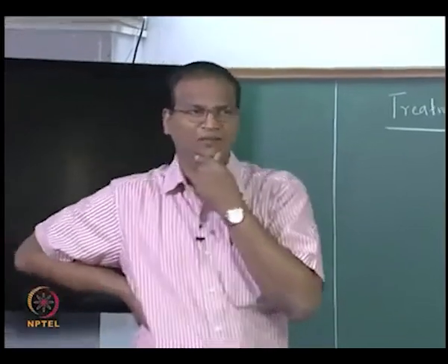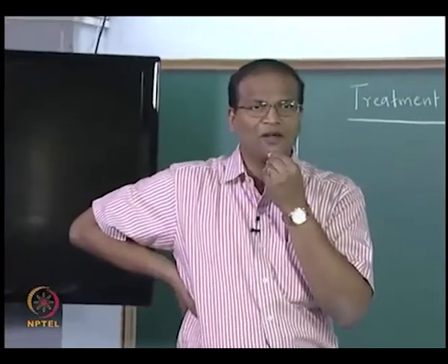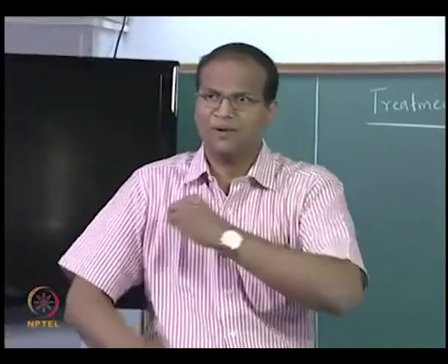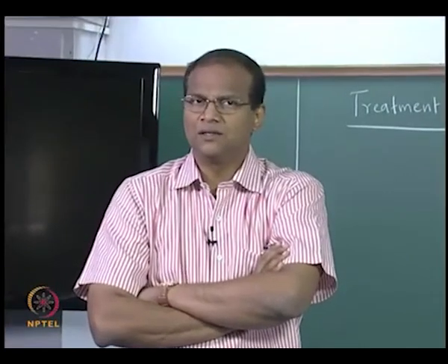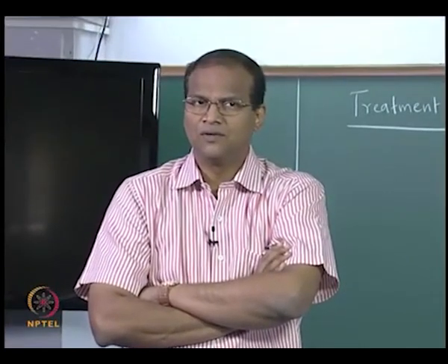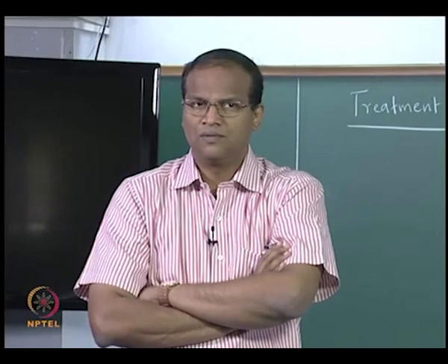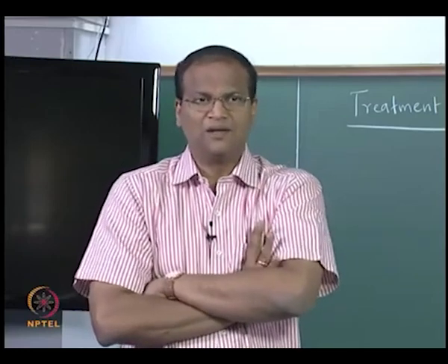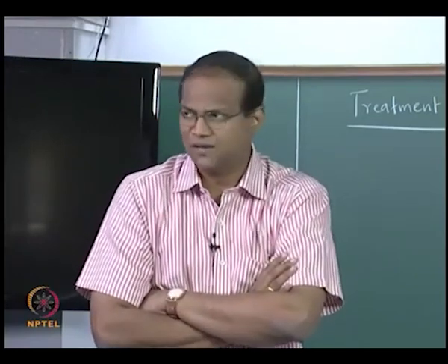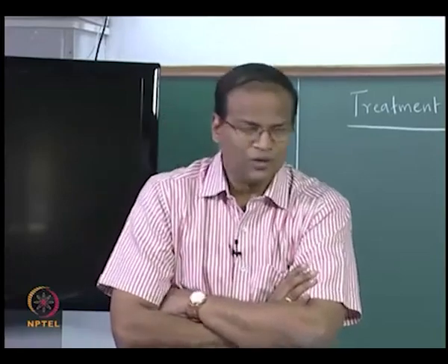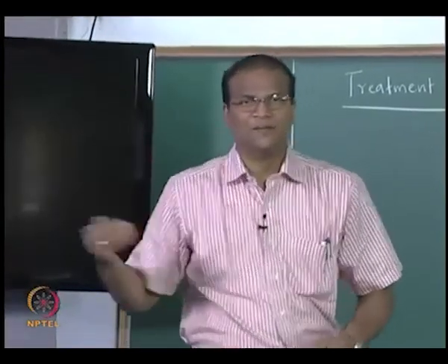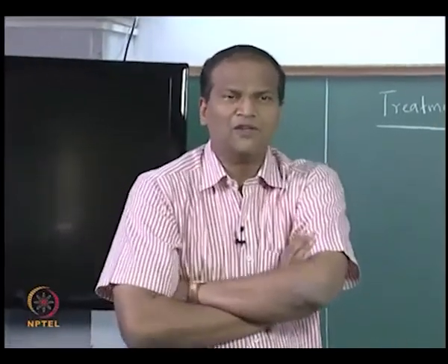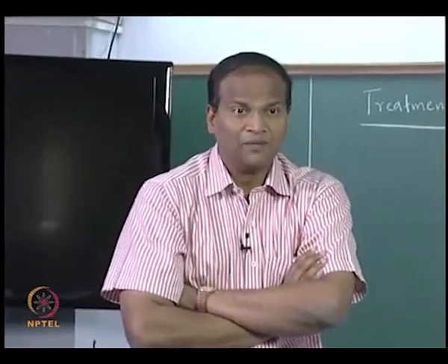Now for a moment, if you pause and think, if you cannot use that epsilon sigma T to the power of 4 because epsilon lambda is a function of lambda, how do you think the formulation will get changed? Epsilon lambda is a function of lambda, so I just cannot use epsilon sigma T to the power of 4 and have one radiosity. So Deepak is coming out with some answers, he is saying that we have to use the F function chart. So if you have to use the F function chart, that means you have to use the F function charts for different ranges of the interval. Are you getting the point?